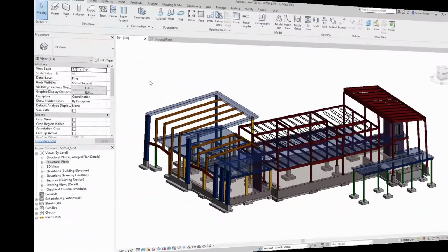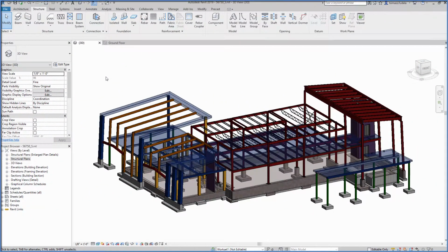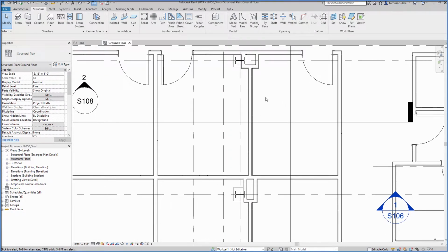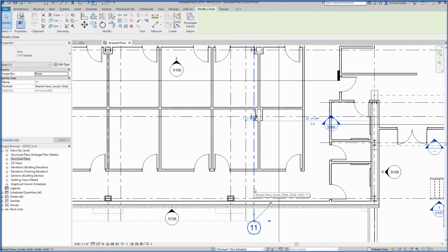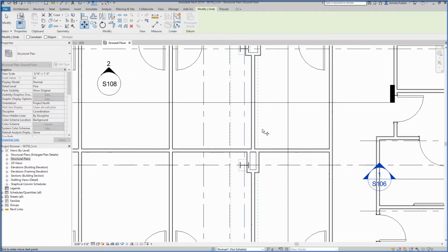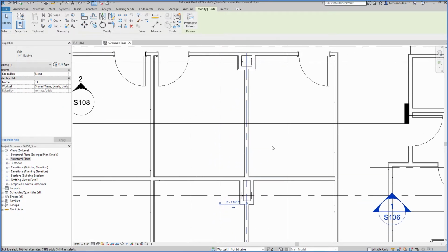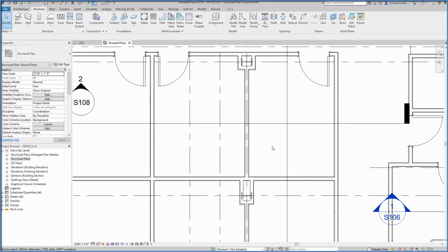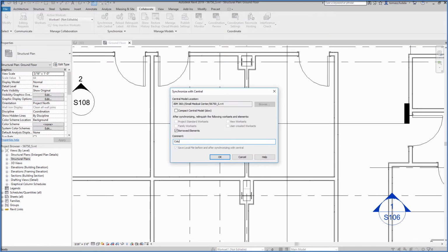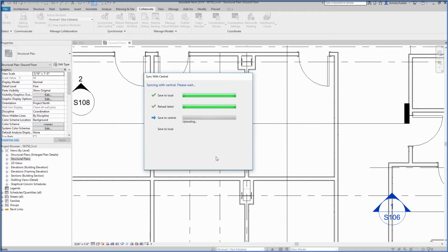If Revit users link into the other team's consumed online models, those Revit links are automatically updated in the team's authoring environment. Now, with the automatically updated linked architectural model, the structural engineer can update the structural model to have it aligned with the architectural design changes. Used together, Revit, BIM 360 Docs, and BIM 360 Design provide better controls, greater data management, and improved design productivity and efficiency through multidiscipline team collaboration.